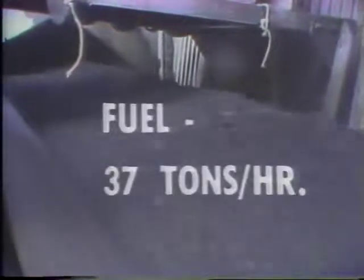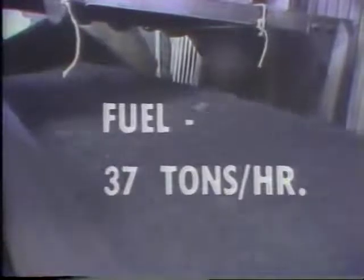In order to produce 100 megawatts, the steam flow through the unit is around 680,000 pounds per hour. Since feed water flow and steam flow must be balanced, the feed water flow is also 680,000 pounds per hour. The fuel requirement for this unit producing 100 megawatts is around 37 tons of coal per hour. To burn 37 tons of coal per hour, the operator has to mix it with about 1.5 million pounds of combustion air per hour.